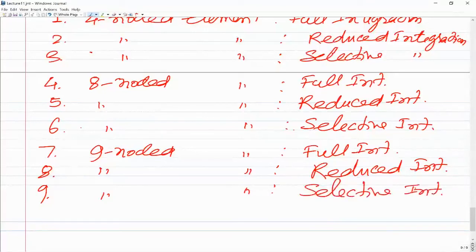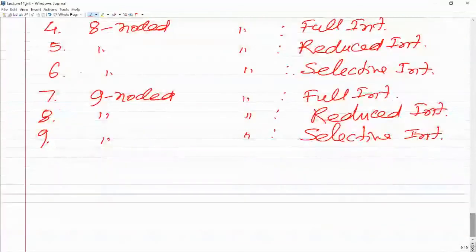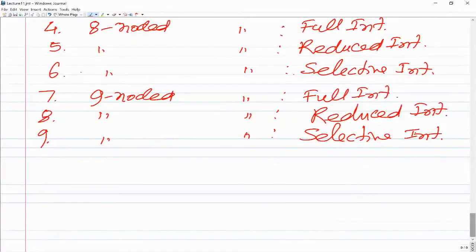So now you can think of working on this. The earlier assignment is on classical plate theory, and this assignment is on first order shear deformation plate theory. Sometimes we prefer to use reduced or selective integration, but then we have to overcome the hourglass problem. There are methods to overcome that.